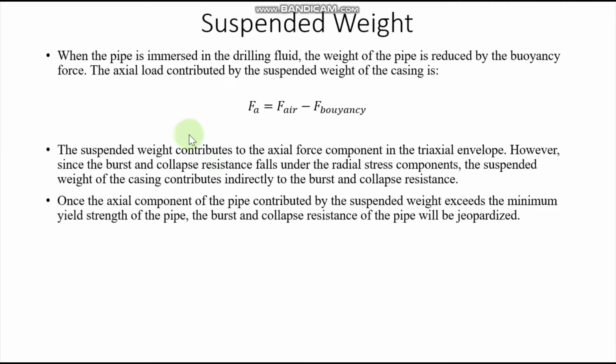Now moving on to the suspended weight. When the pipe is immersed in a drilling fluid, the weight of the pipe is reduced by the buoyancy force. This takes into consideration the real case scenario where, in the well, we have the drilling fluid supporting the weight of the casing as well. So the axial force contributed by the suspended weight of the casing is given by the weight of the pipe in the air minus the buoyancy force acting from the bottom of the pipe. So the suspended weight contributes to the axial force component in the triaxial envelope.